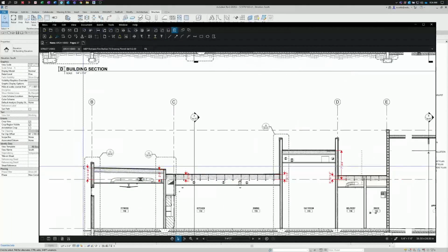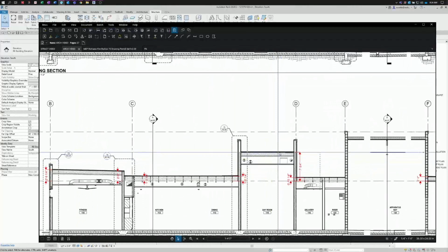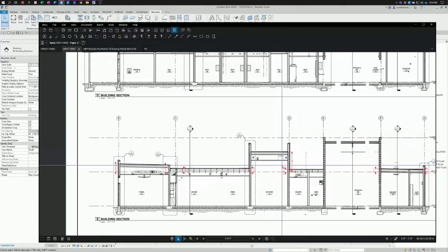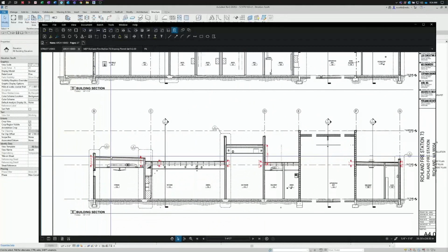The first one is here at the far end at 2'9", and then I have a higher bay of joists that'll be a little over 7 feet. So those are the 2 I'm going to add, because when making a view, I want to cut at the highest location above the joists that I want in my plane. So those 2 will be used.